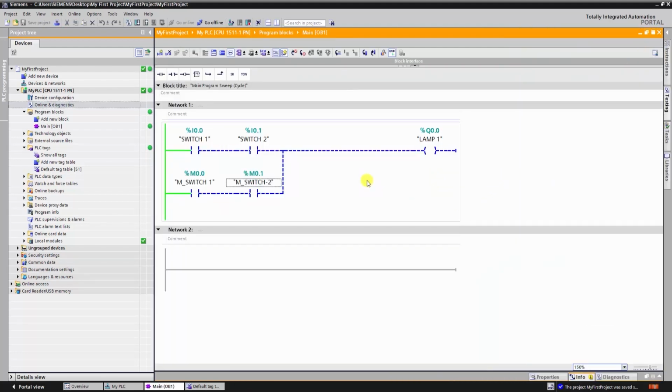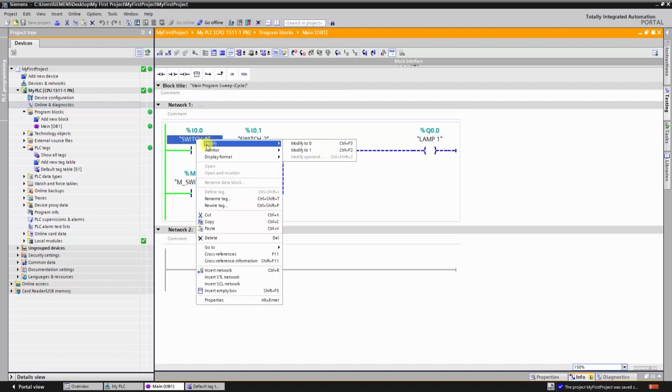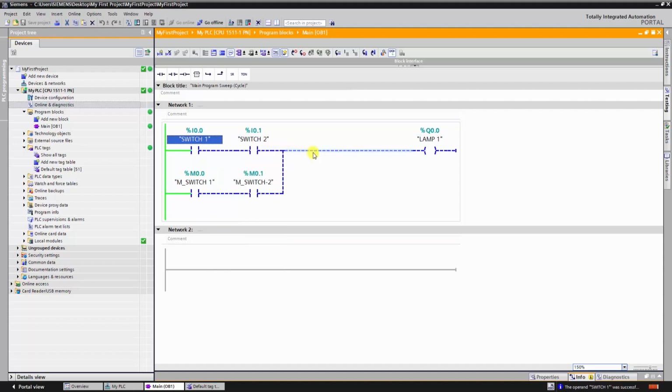The test of our code consists of changing the state of inputs, and checking if the output state will change as we want or not. It is not easy to modify the physical input state, because, simply, the PLC reads their state from the digital input module. That's why we inserted in parallel internal tags, which are easier to change their state during the test procedure.